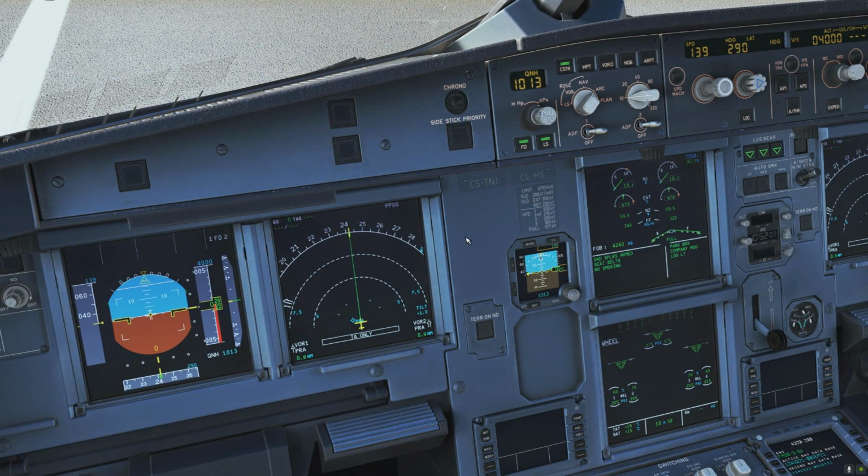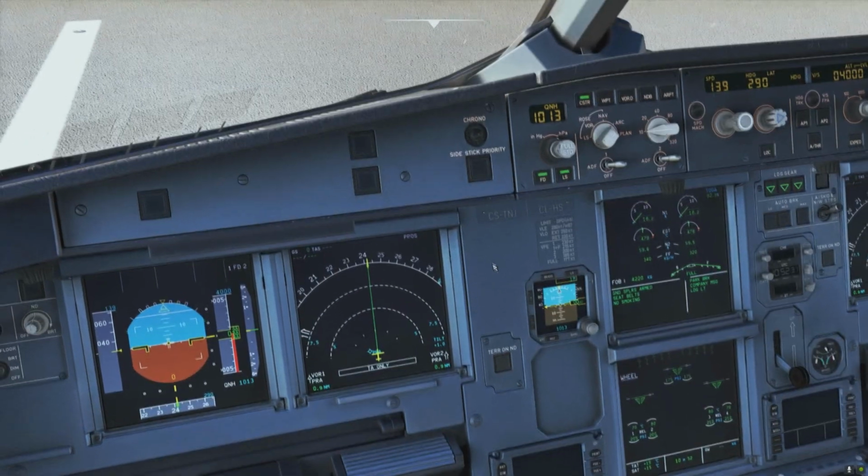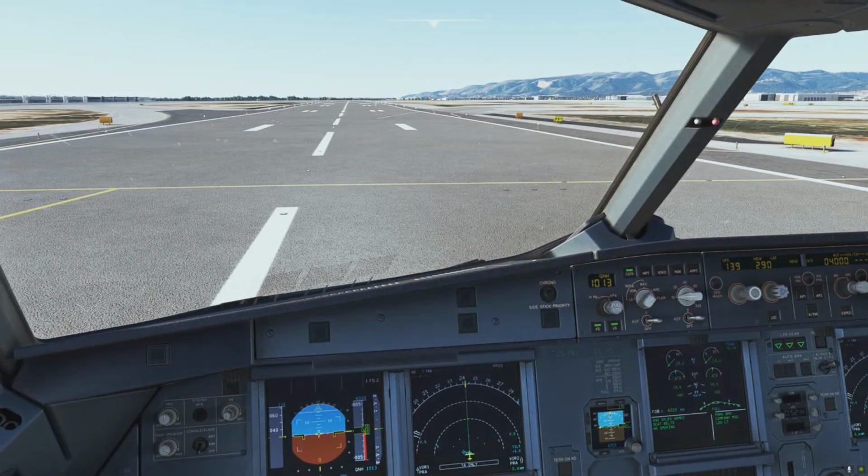One last thing maybe that we haven't really talked about too much, and that is wind. Winds can be very strong. Take them into account. If you have a lot of tailwind, be a bit more conservative, because it will blow you to the runway very quickly. And if you have a lot of headwind, there's nothing wrong with doing everything a little bit later, especially if it's a huge headwind. We have that sometimes, I don't know, 40 knots headwind at 3000 feet. Your ground speed is something silly like 100 knots, 90 knots. It's almost like the speed of a GA aircraft.